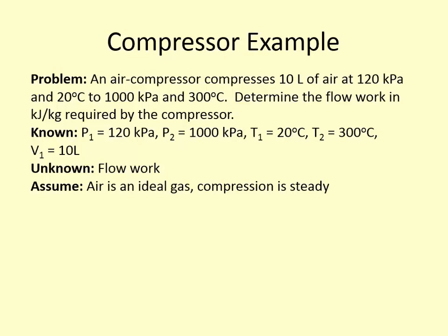So you can fix the initial state, and then it leaves as a superheated vapor at 0.8 megapascals and 60 degrees Celsius. So superheated vapor, and you're given the pressure and temperature. Can you fix the state? Yeah. Okay, so instead of plugging in RT2 minus RT1 using the ideal gas equation, you have to actually find the pressure and specific volume at each of those states. It's not any more difficult to do, really, if you know what you're looking for.